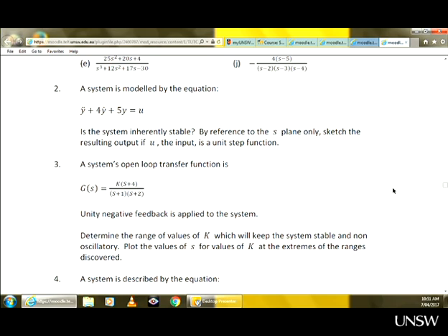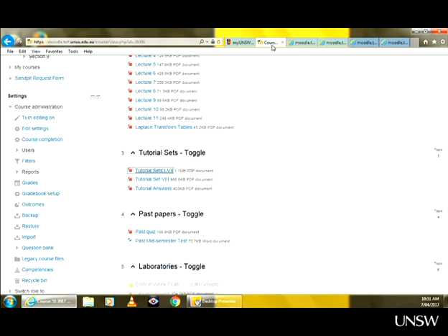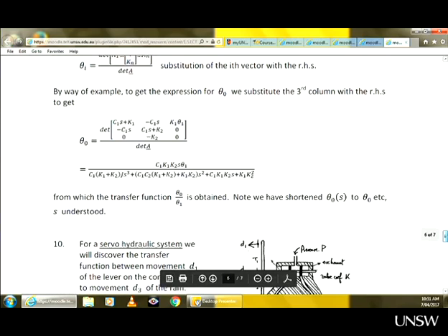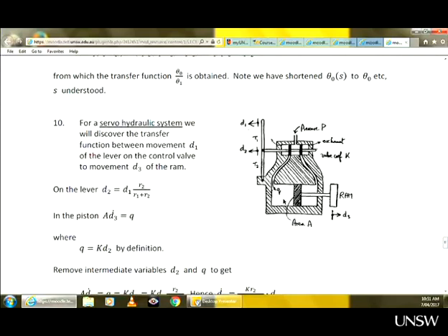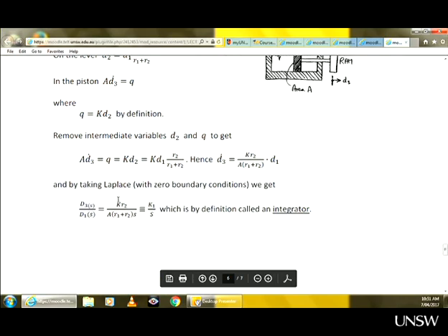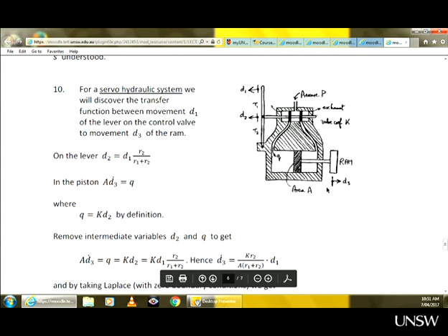So the damper is an integrator. I had one example somewhere back in, I think, lecture 5, at the very end of it. Yes, this is an integrator. This servo mechanism is an integrator, because when we derived the transfer function, we got this. Everything is constant apart from that. So this is an integrator, but you can also have an electronic circuit that acts as an integrator. They are much smaller, it's just hard to visualize.